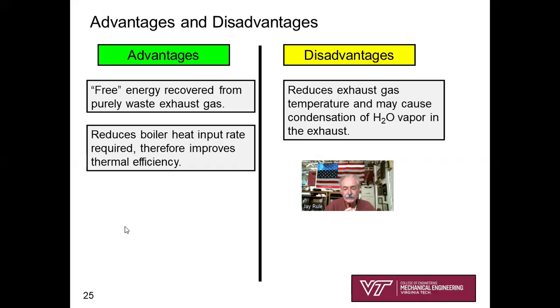So operationally, we have to be careful to not pull too much energy out of the exhaust gas such that H2O vapor, a natural exhaust product, right? H2O is a natural exhaust product of any hydrocarbon fuel. We don't want to condense that vapor out of the mixture before sending it up to the surroundings.